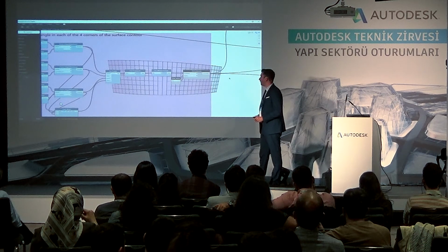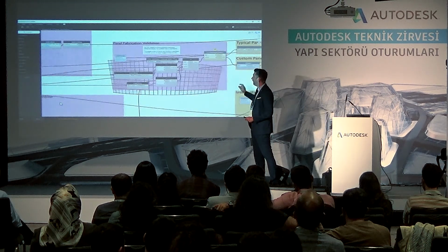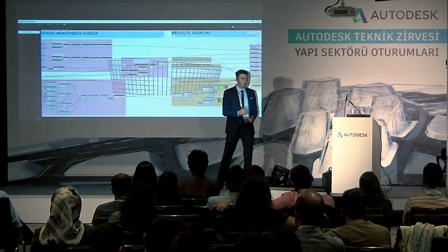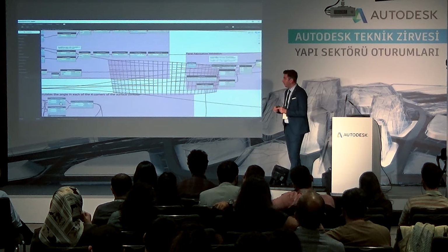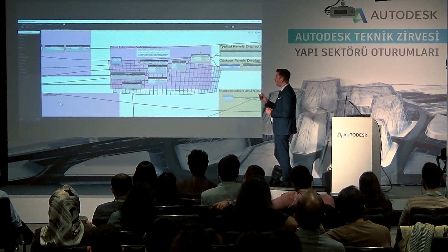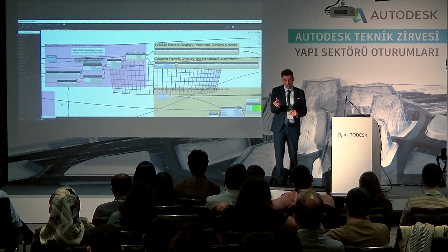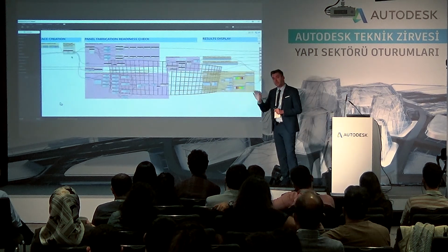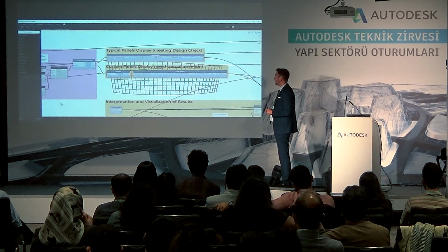And in the end, we can use color coding, you saw there, to color the panels that are rectangular and easy to fabricate. Planar deviation is 0 or under a certain limit, so we can specify the planar deviation. If it's higher than 5 millimeters, highlight that panel, and it means that panel is more difficult to fabricate.